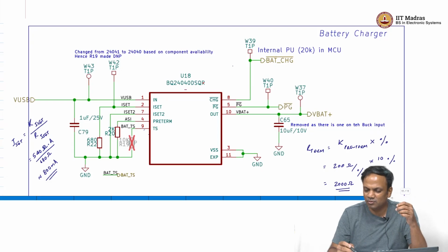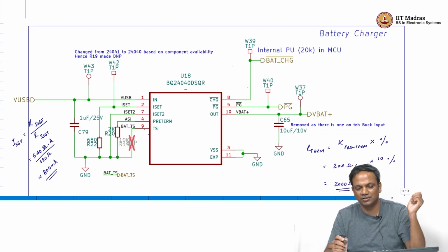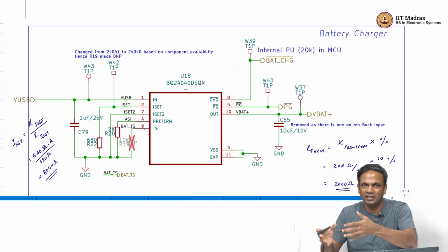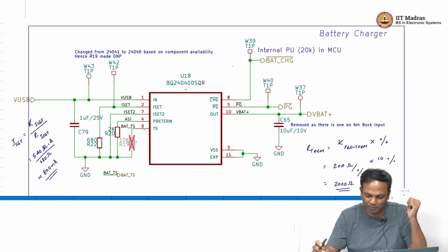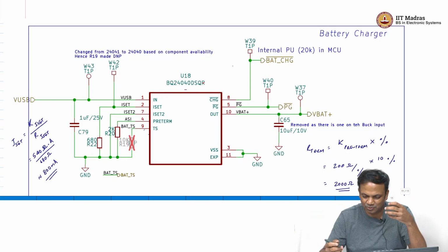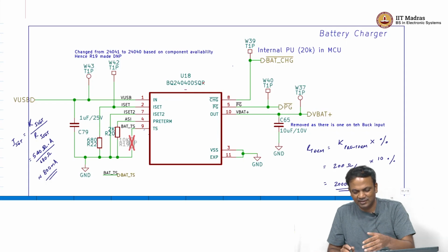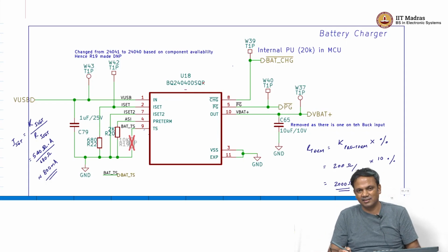That is what the statement here says: there is an internal pull up in the MCU, a 20 kilo ohm pull up resistor. If the switch is off, that pull up resistor ensures that node goes high for any subsequent logic operation. There is a power good pin which is just connected to power good, available for the MCU to take some action if needed. And then there is the VBAT, again ignore the text, and VSS is connected to ground.